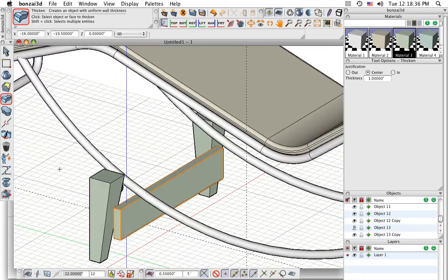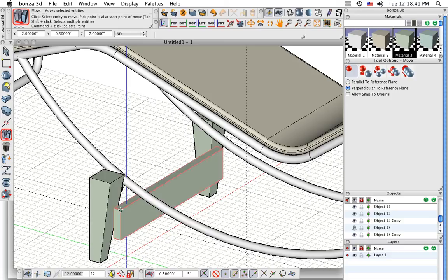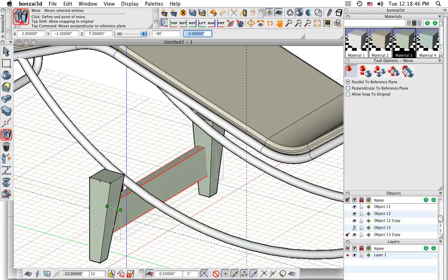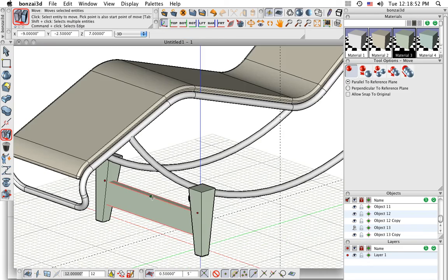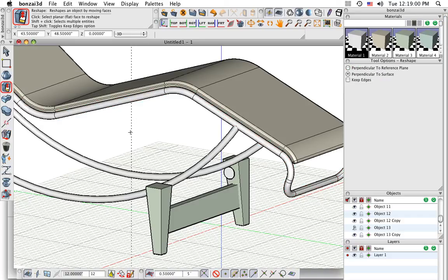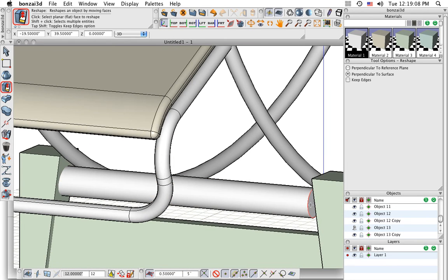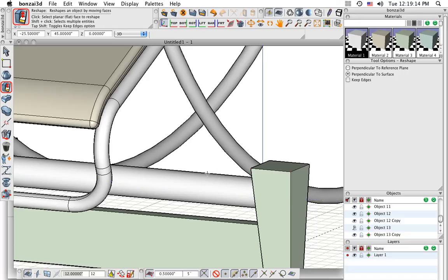And now let me move it into the center. Use the move tool. And snap to the center point here. That looks good. Okay. One more piece I need to extrude down here. This little circle will become the frame support. Give it a different color first and extrude that. And I purposely extrude this all the way into the leg piece here, and same thing with the other side. Click on the end face here and extrude it all the way to the middle here using snapping.